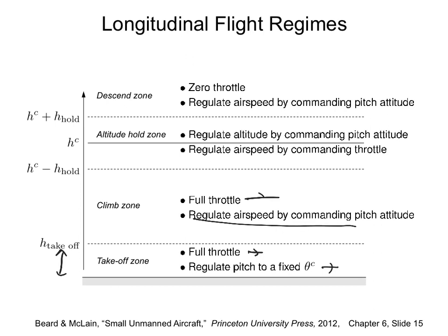Otherwise, how would you change your airspeed if your delta T is already 1? Airspeed can be changed by throttle. If that is full, maximum, but you still want to increase or decrease your airspeed, then you can use pitch angle. So you can compute your desired theta for desired airspeed, and then call that pitch loop to compute your elevator commands.